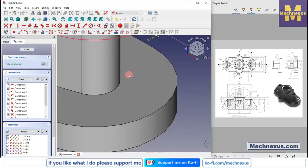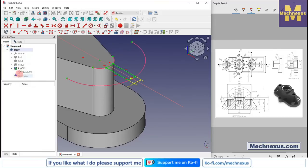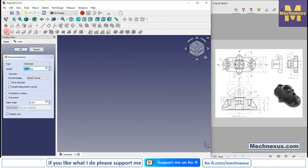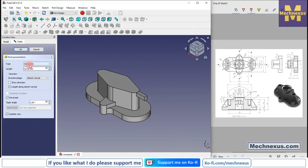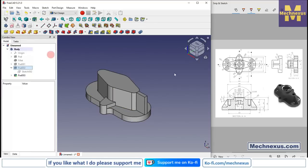We will press 0 for isometric, and we will go to the model tab. First we will exit and select the sketch and click on the extrude, and from here we will select the reverse, and from here we will select up to face and select this face, click on OK.